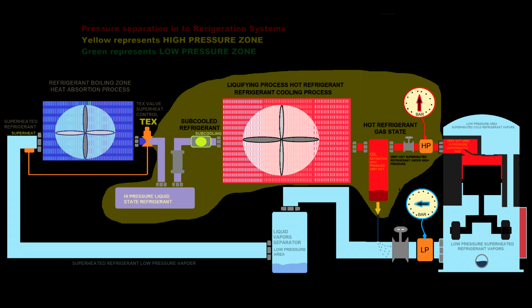You have to control the amount of liquid that goes out at that point, because sometimes we have very long piping and we have to make sure that we don't starve the compressor. Near the valve of the suction line, near the LP, when we check the superheat, ideal will be to have 10 degrees over the boiling point of the refrigerant. But as I said before, I can't give you numbers because I don't know what type of refrigerant you are going to use. For that operation, you have to use refrigerant charts.